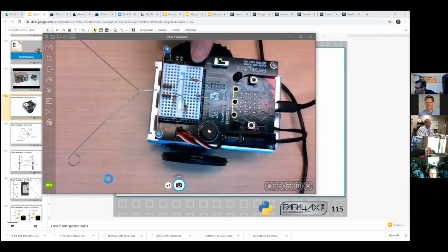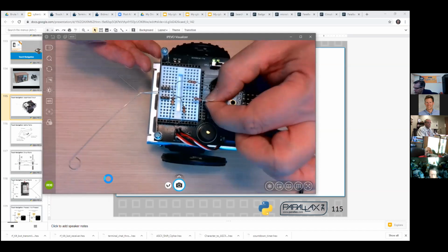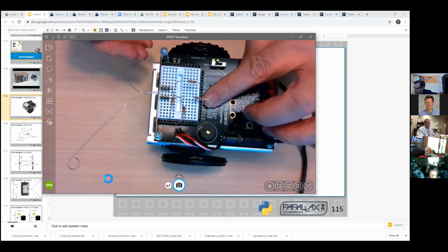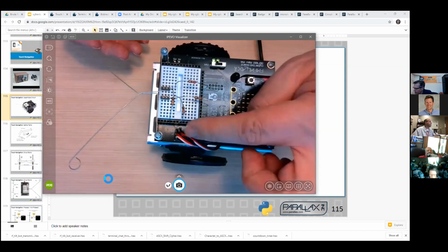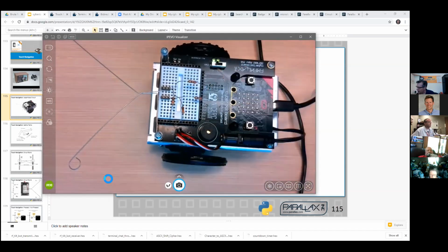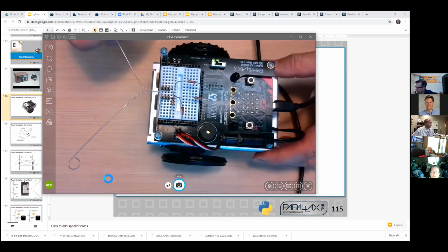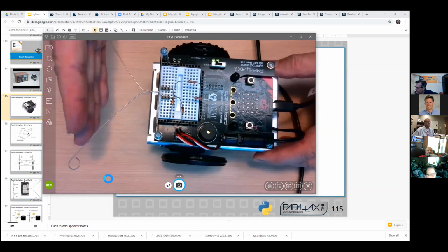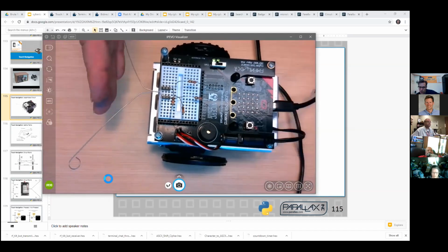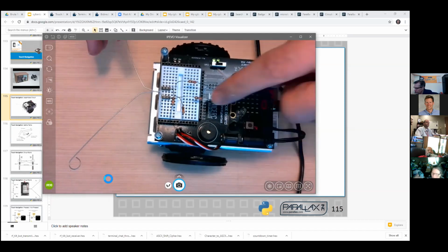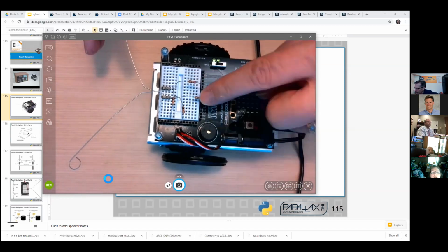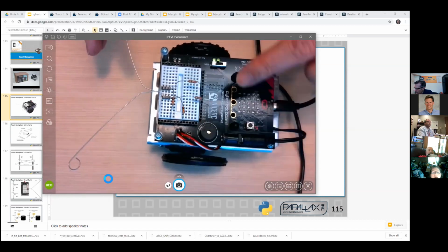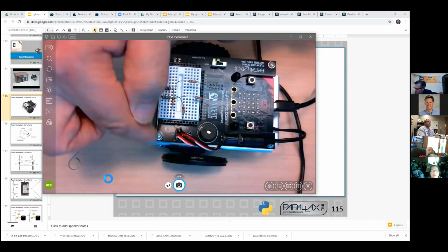And so that's when this socket is having 3 volts applied to it from up here. It's going through this resistor and through that resistor, and it's just sitting there. That voltage isn't really running any current. It's just sensing 3 volts. Now, when I close the connection, when the robot runs into something, you see how it pushes the whisker against the wire? That's when all of a sudden the circuit is now changed so that it's 0 volts, that 0 volts is detected right here. And there's actually 3 volts now driving some current through this large resistor and into ground.